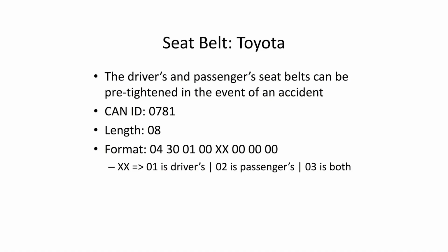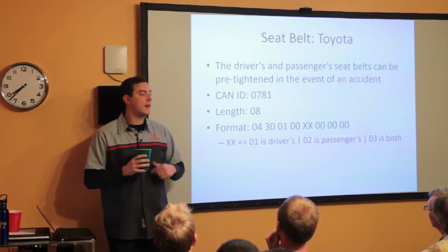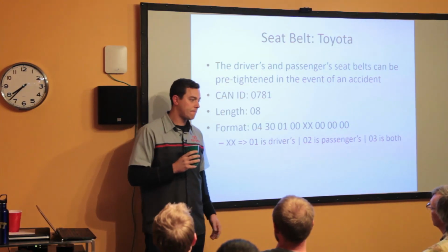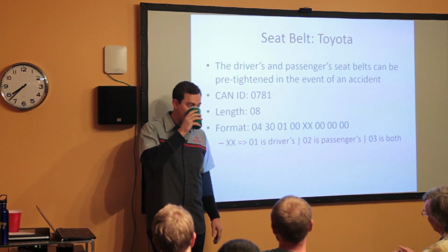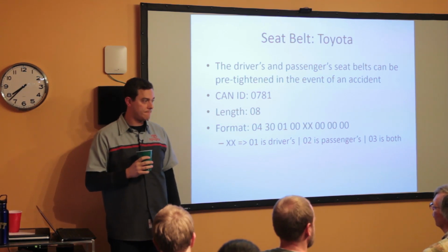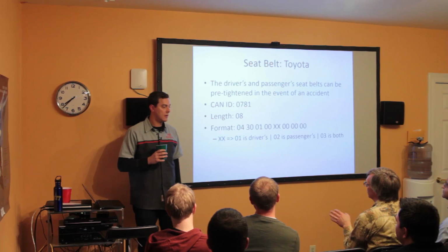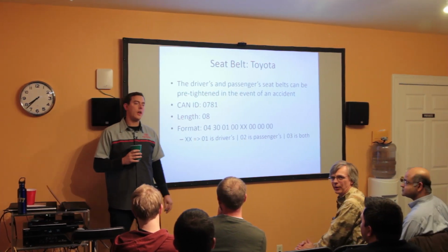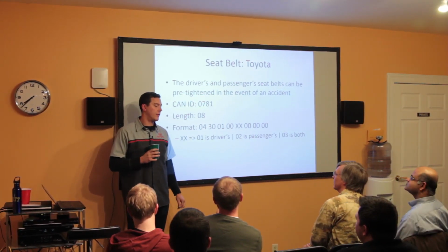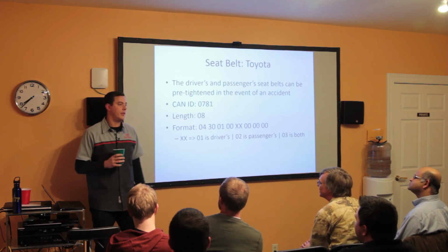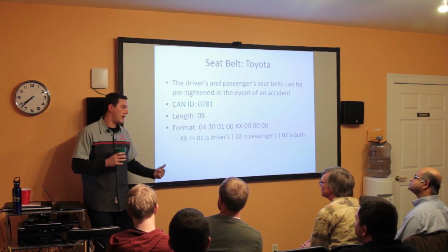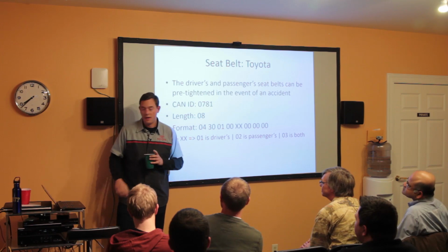In a lot of vehicles, if the CAN bus is active, nothing goes to sleep. Well, I don't think some things broadcast messages anymore. At least in the GM and Chryslers, the entire vehicle wakes up when you get a CAN message out there. So be careful, you can end up flattening your battery. That's not how the Toyota worked, because you could send CAN messages, and I'd go up first thing in the morning and try CAN messages and nothing would happen.